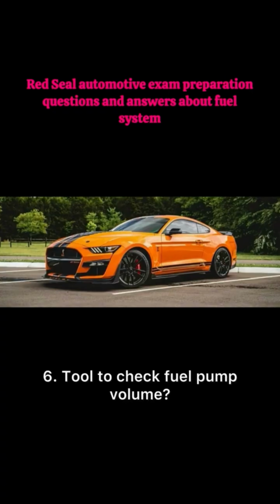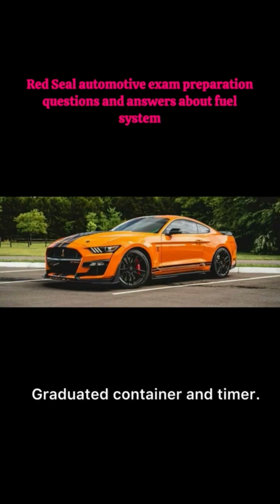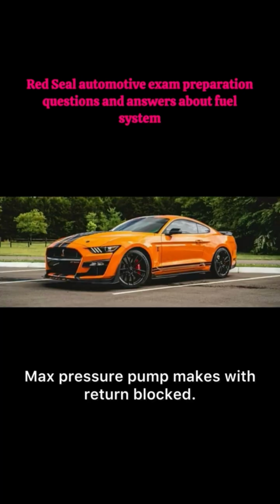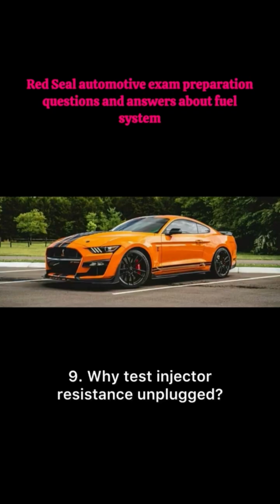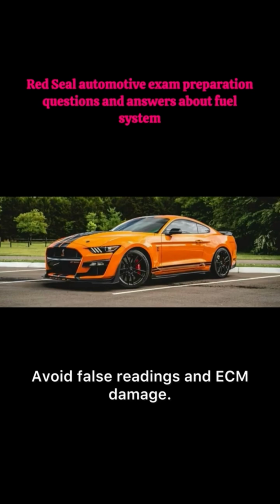6. Tool to check fuel pump volume. Graduated container and timer. 7. What is deadhead pressure? Max pressure pump makes with return blocked. 8. P0442 code means. EVAP small leak detected. 9. Why test injector resistance unplugged? Avoid false readings and ECM damage.